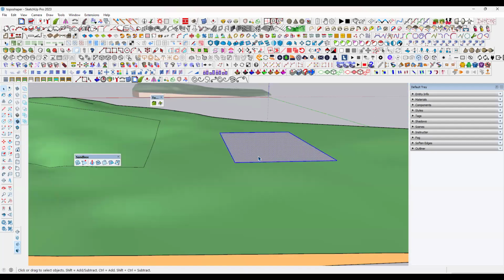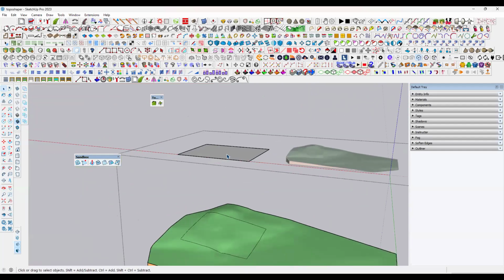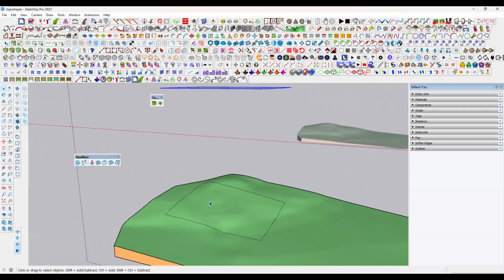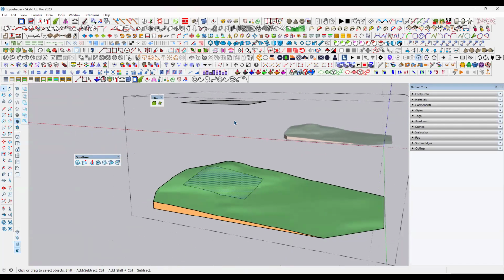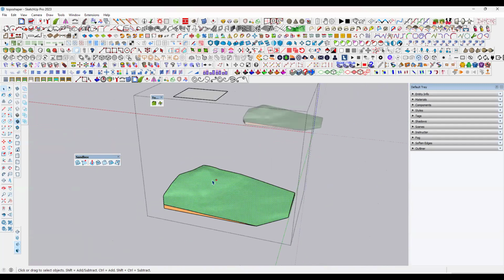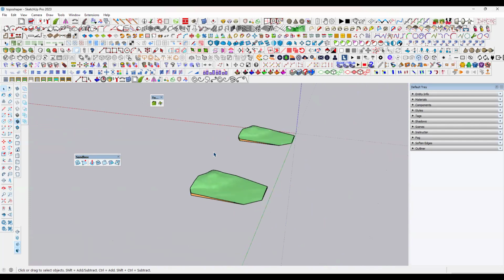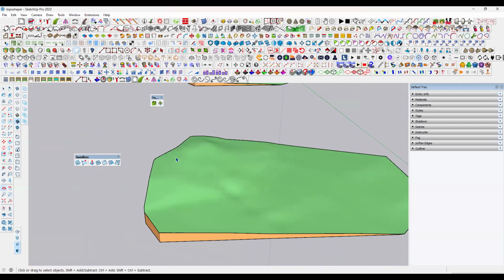Okay, now, we can't make a separate portion out of here. But with the help of this one, what I have done, we designed one rectangle on the top surface, and here we have an exact imprint. So I have taken an imprint of this shape onto the irregular surface, the contours, or maybe the landscaping surface. Okay? So like this, without the help of this topo shaper, we can't create this kind of a